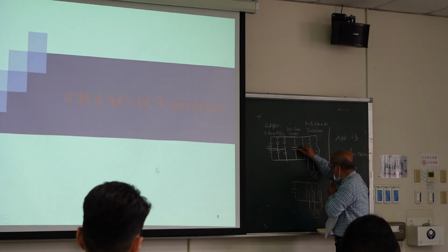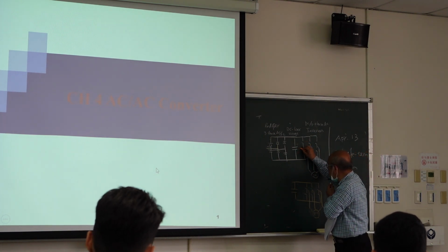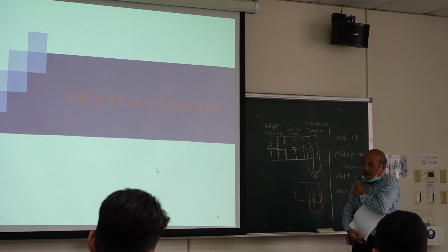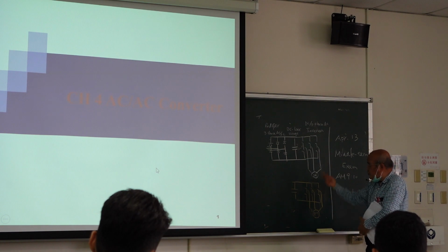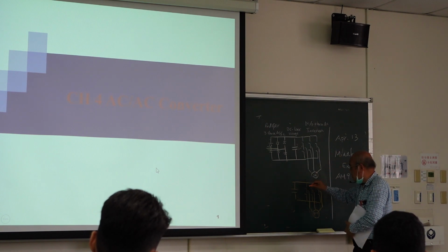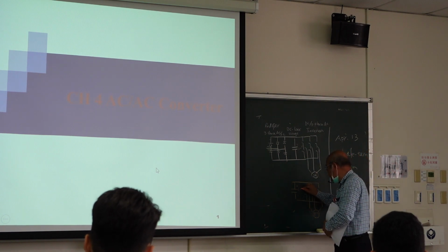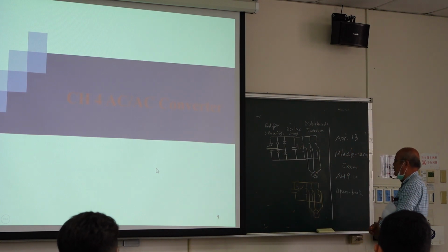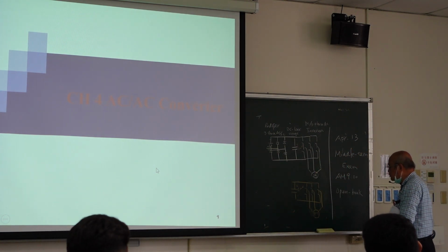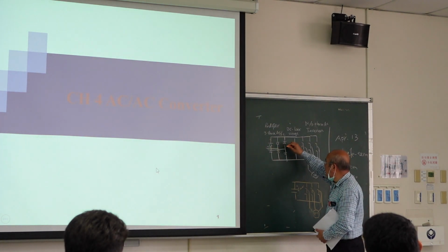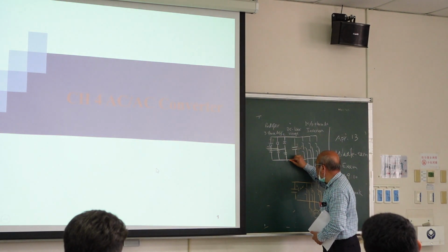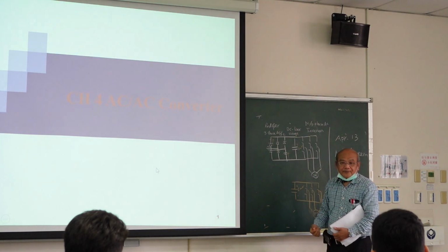Before, here could be 300 volt. But now you need a PFC, right? You have to increase your voltage, so it could be 600 volt, double. If you need to do PFC, you cannot use a diode, because a diode only goes one direction, right?